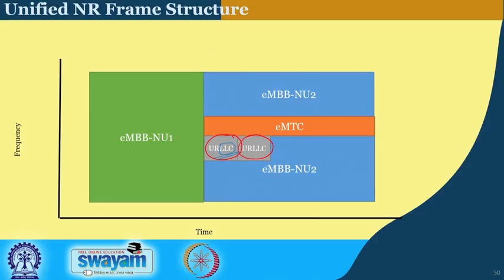So, in a typical communication system, a slot is the unit which gets addressed. In the earlier generation there was a subframe, of 1 millisecond duration, which was getting addressed. Now, you can address a slot, that is point number 1, but look at the flow of things when it goes from Tx to Rx. An entire transmission unit has to be decoded at the receiver.